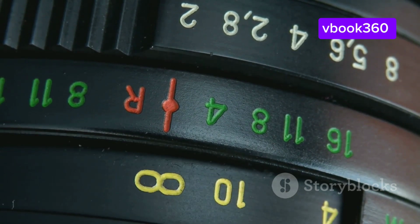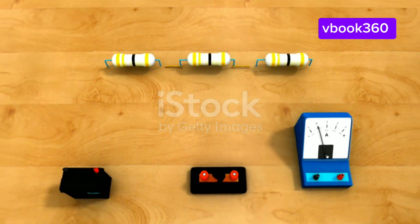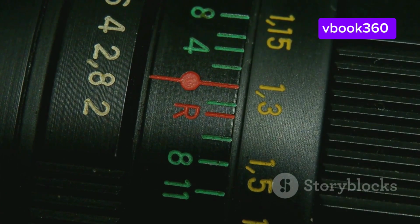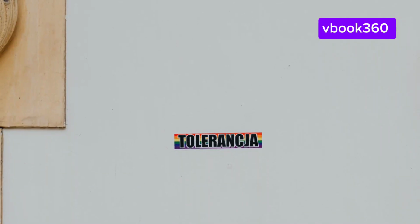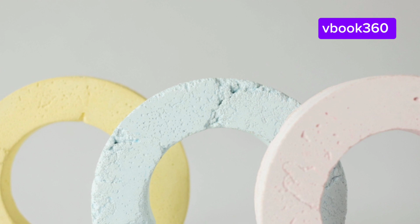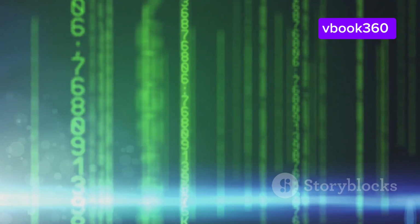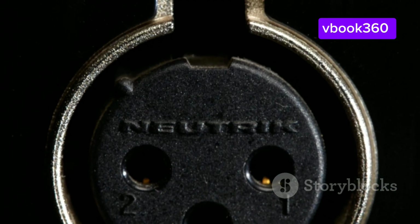When deciphering the resistor color code, it's crucial to remember that the position of the bands is paramount. The color bands must be read in the correct order to determine the resistor's value accurately. To ensure you're reading the bands in the right sequence, identify the tolerance band first. This band, typically gold or silver, will be slightly separated from the other bands and will always be the furthest to the right. Once you've located the tolerance band, you can then read the remaining bands from left to right, starting with the band closest to the edge of the resistor.